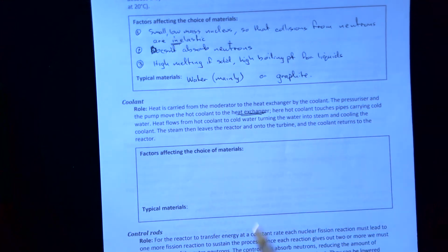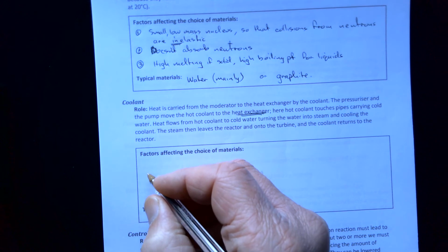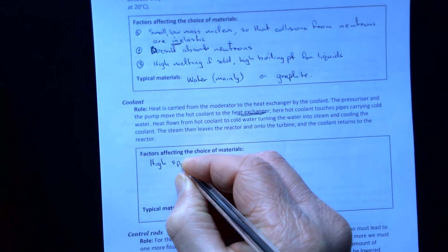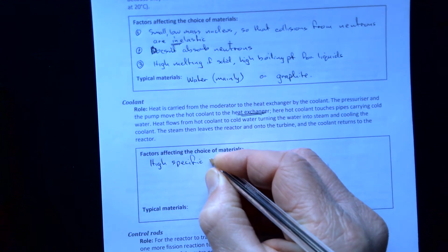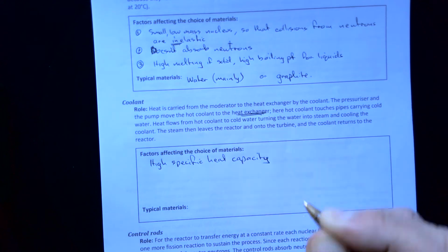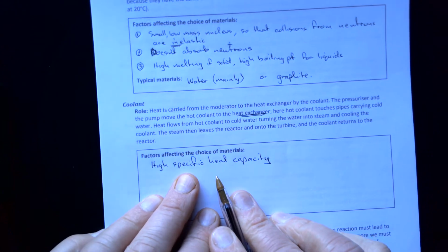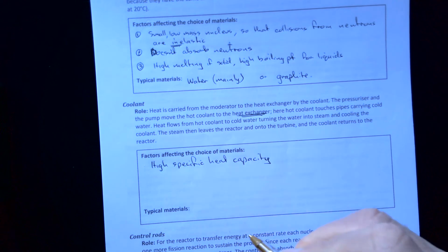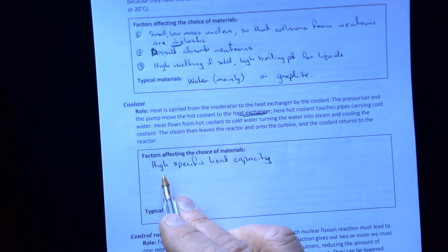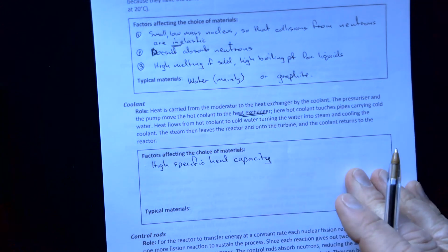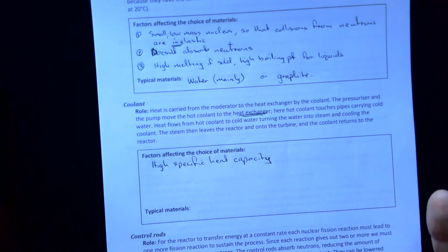And I said it touches the pipe, but it's in contact with the pipes, so it can absorb as much energy as possible. As you want it to absorb as much energy as possible, it needs to have a high specific heat capacity. That is its main function. That's going to absorb a lot of energy without getting too hot, and therefore it can take that energy away and deliver it to where it's needed. Okay, so it's a high specific heat capacity and it needs to be able to flow, so it has to be a fluid, liquid or a gas, as it goes around the pipes, kind of obvious.